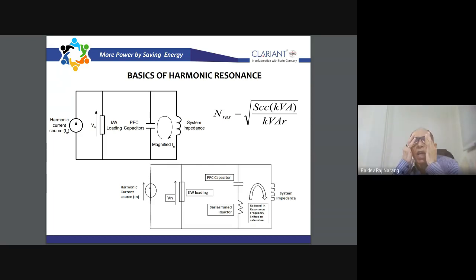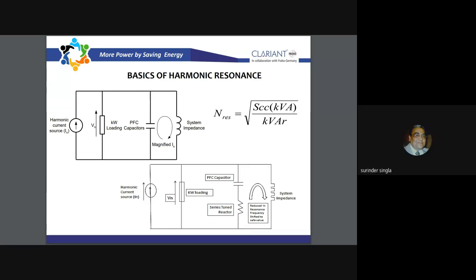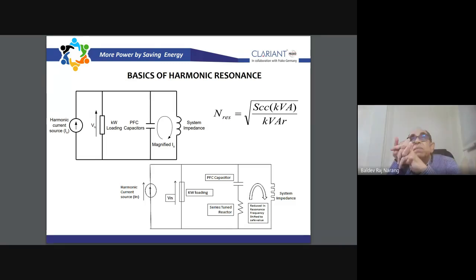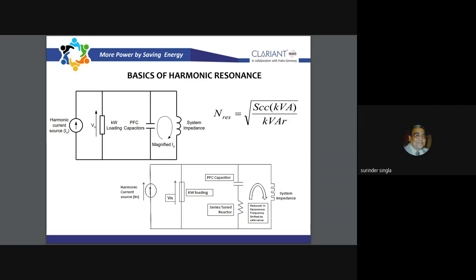So energy auditor, yes sir, has a role, basically their purpose is to do energy saving. No, we do identification. We tell it is the third harmonic, fifth harmonic, seventh harmonic. We tell them this is a voltage harmonic, this is current harmonic. But when it comes to the designer, when you have to design it, you have to put that in system. As far as the power factor is concerned, we are almost certain that okay, you put this and this, the things will improve. But in harmonics, it has been observed, it's still a very dicey factor.